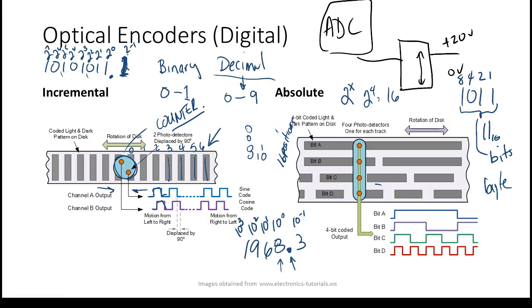So if I've got electronic counters, which are digital counters, and you take power off those counters, then they're going to lose their count. Not even reset it. Literally, if you turn a digital counter off and you put power back on it, the count comes up to be what we call random, unless you reset the counter. So you can have some type of circuit that would automatically reset the counters if you want to do that. But anyway, the number that you get is a random count.